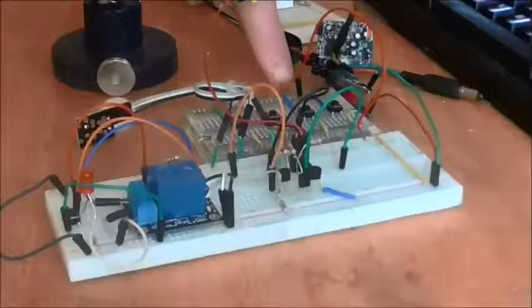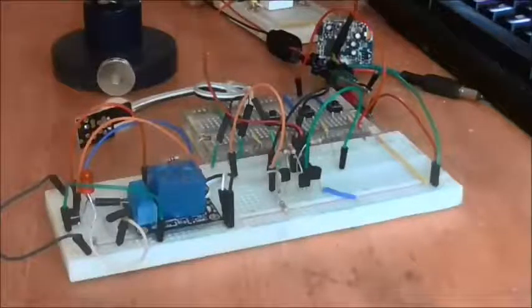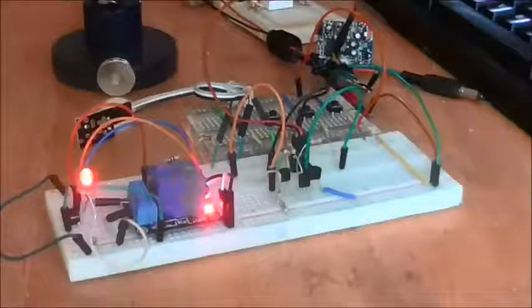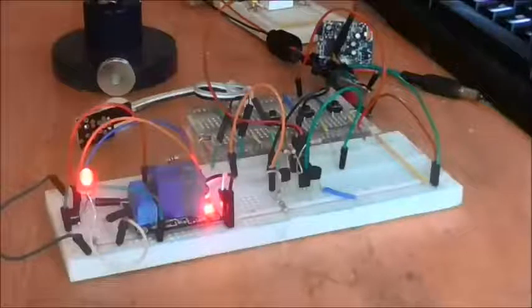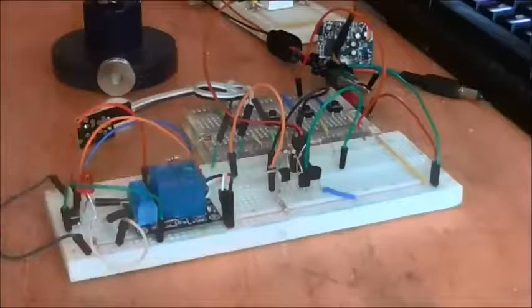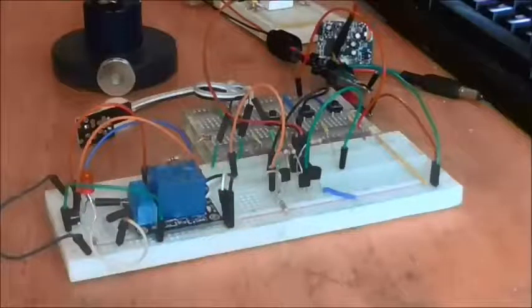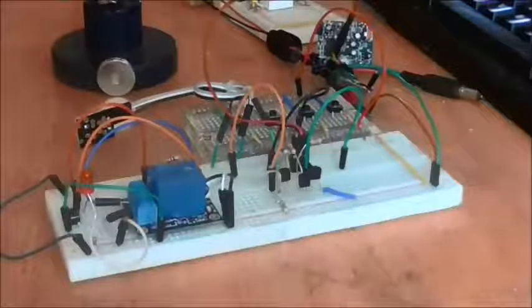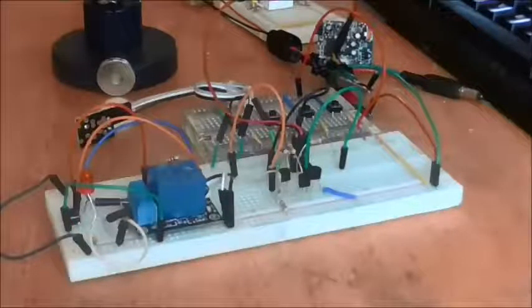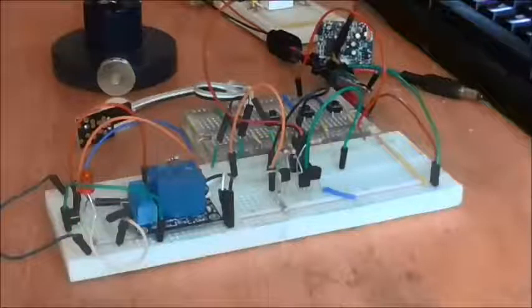Well, it certainly works. So the next thing I really need to do is I need to put that output to a transistor and see if we can drive a siren with it, working on 9 volts. After that, because it's looking a bit ungainly at the moment, what I'm going to try is doing the same with quad NANDs and see if that works any better.